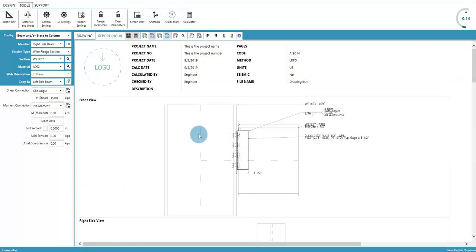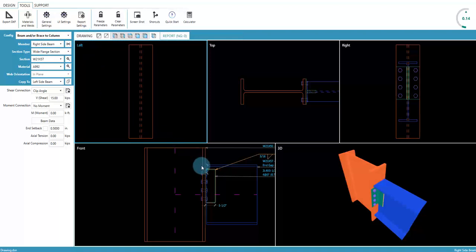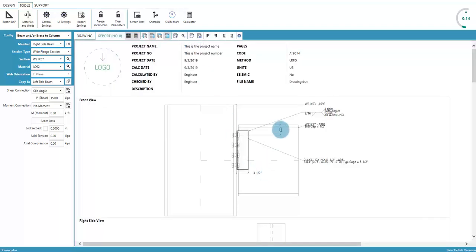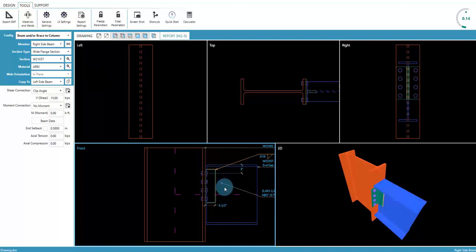Descon automatically arranges the callouts and dimensions focused on being legible and compact. However, if any modifications are needed, simply open the Drawing tab just before printing and drag the dimension or callout. The arrow can also be moved and will always be pointing to the correct connection element.